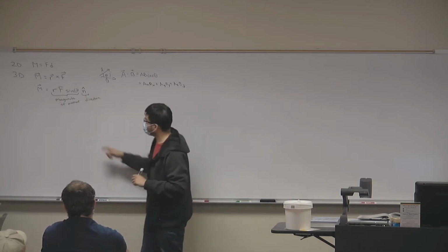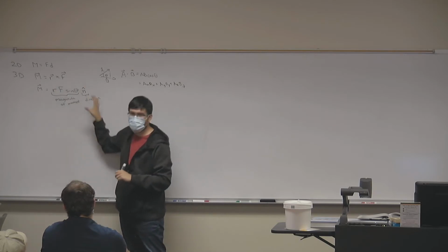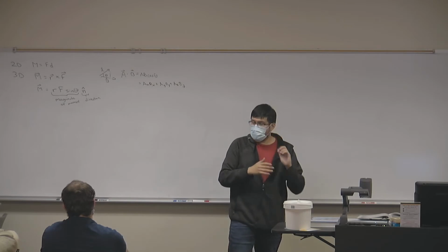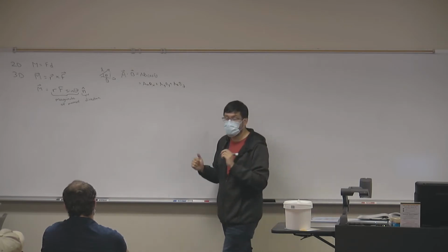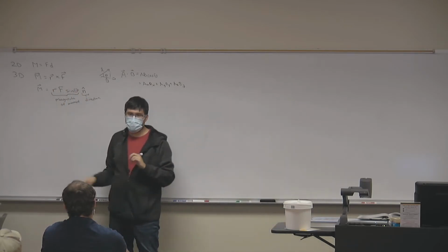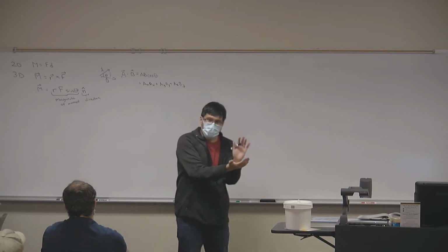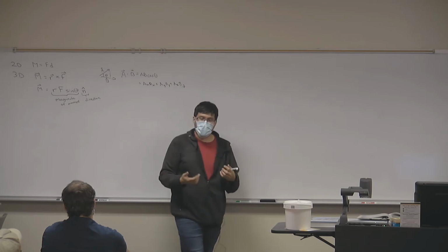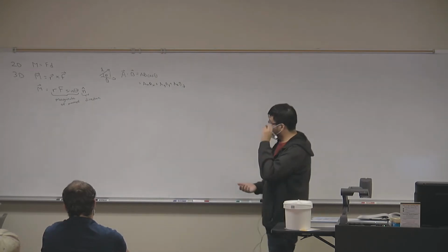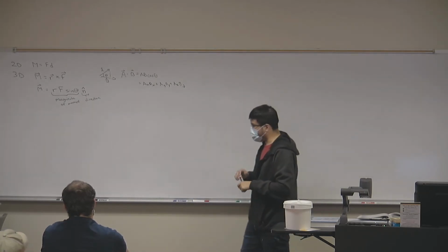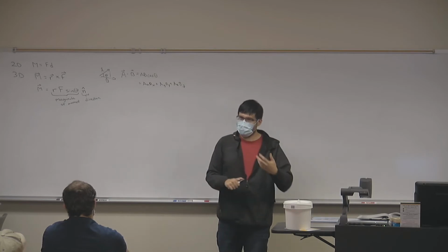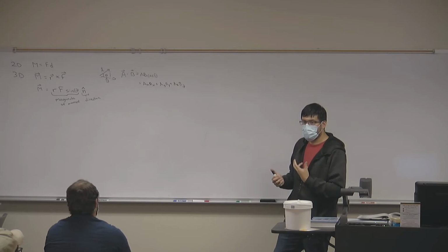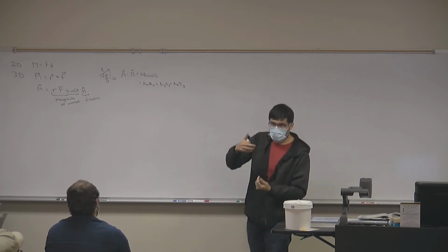Because at 90 degrees, the sine of 90 is 1, and this is the largest number. What that means is that if two vectors are perpendicular to each other, that's the most tendency of rotation we can have between the two. The closer the vectors are to each other in direction, the smaller the moment, so the smaller the tendency of rotation. When you get to your more advanced classes, particularly fluid mechanics, which is my favorite class to teach, we use the cross product to determine the vorticity, that is the rotation of a fluid.